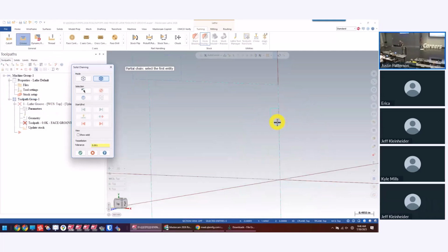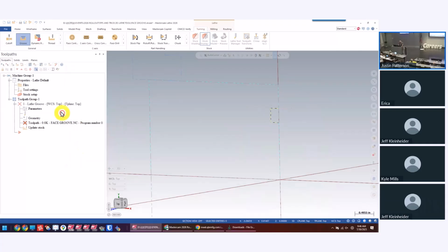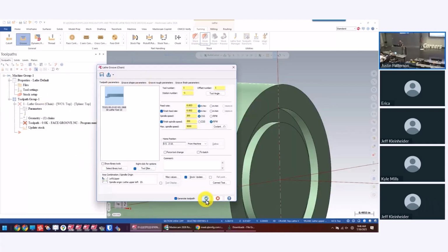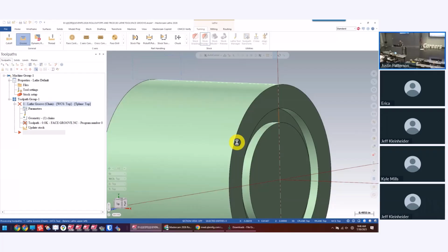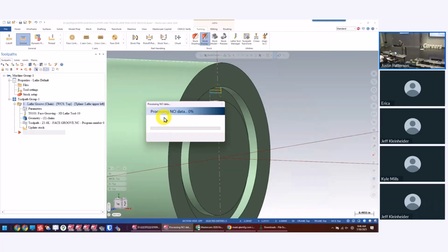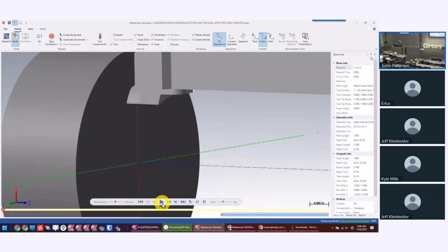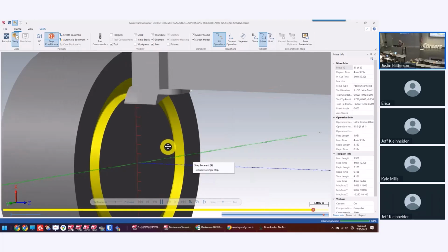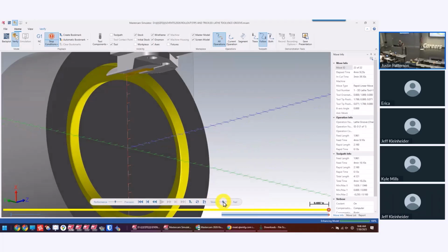Okay. So we go from there to there. Pick that tool. I'm just going to green check. Okay, looks good. But when we go in here and we run our verification, we're going to stop on collisions. We will see. We do not. I must have moved that on me. But I thought I had it correctly, but it'll actually alert you saying that you have a collision with the tool holder hitting, because it's looking at that 3D tool now. I can't remember what I did last night.